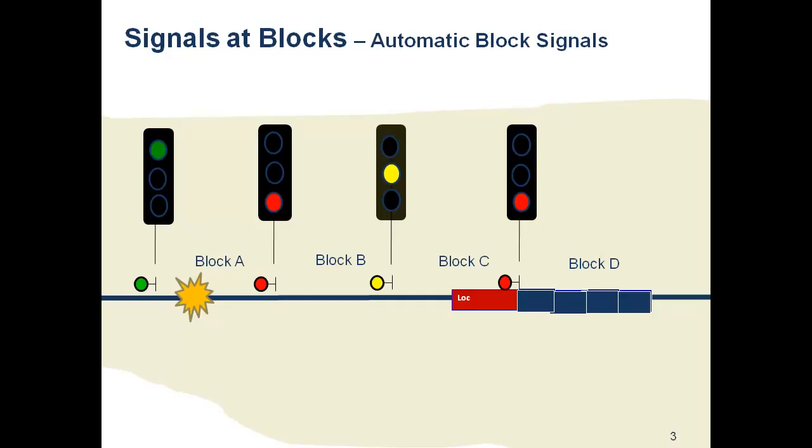And is it typical that the train engineer is the first to become aware of a signal change within a block? To answer that question about who becomes aware of what and when, this depends on the sophistication of the dispatching control center. When something anomalous happens, ideally the dispatcher control system would display a red light on the control board in a particular block. An alarm would also be transmitted to the dispatcher in some way.